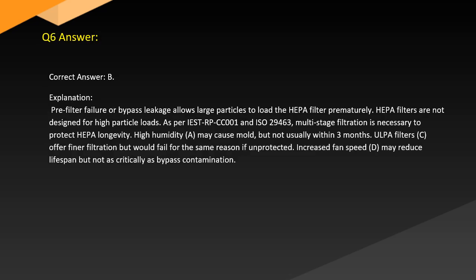Answer. Correct answer: B. Explanation. Pre-filter failure or bypass leakage allows large particles to load the HEPA filter prematurely. HEPA filters are not designed for high particle loads. As per EN 1822 and ISO 29463, multi-stage filtration is necessary to protect HEPA longevity.